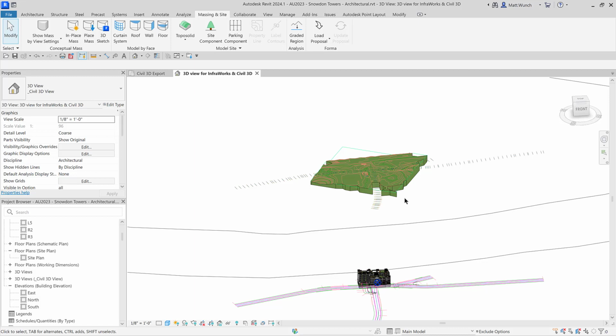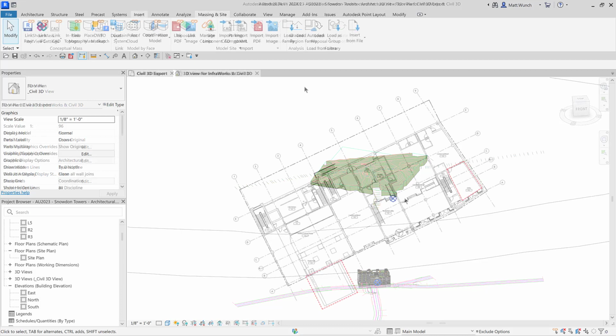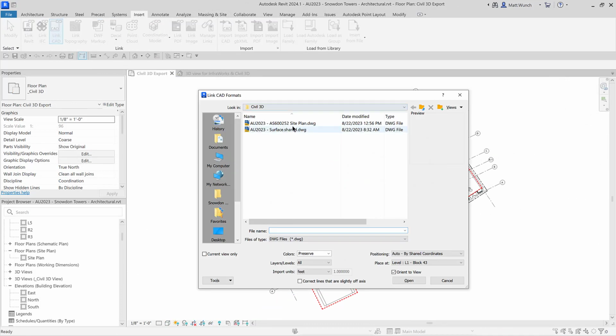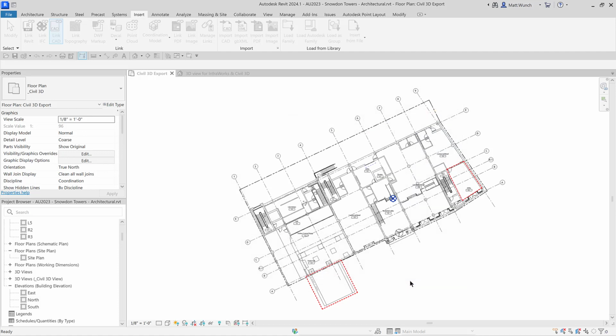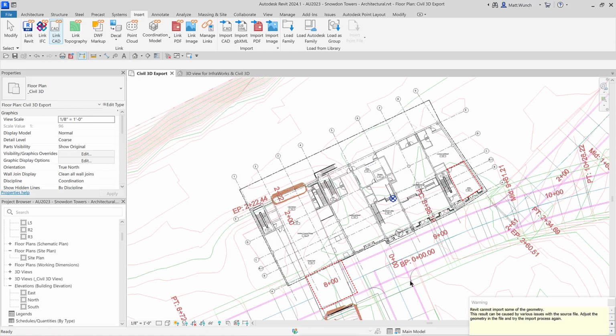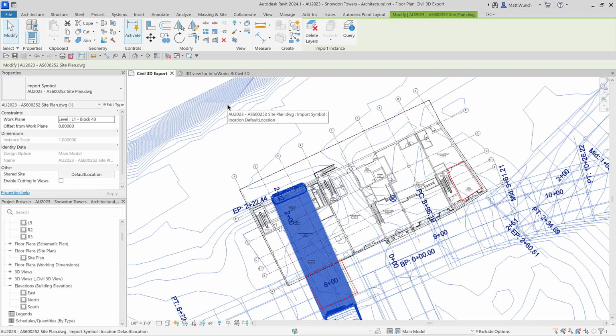This is because when we link the DWG into Revit, we placed it at the same floor and elevation that we used to initially set our models, which was 780.5 feet. And because the contours in Civil 3D are elevated, we need to adjust vertically minus or negative 780.5 feet to move them down to the same elevation as our finished floor. So let's undo the Toposolid creation and redo the process, but this time we'll set the DWG at the correct elevation, which again is minus 780.5 feet.